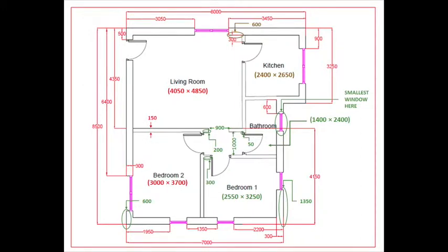sides of the interior partition. As an aside, I noticed that the exterior walls are very thick at 300 mm. Being a civil engineer, I know that this is very unusual. Normally, walls will be around 100 to 200 mm, wherein the exterior will only be about 150 and the interior will be around 100.